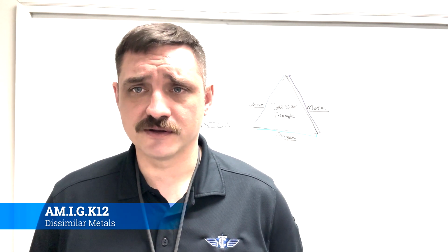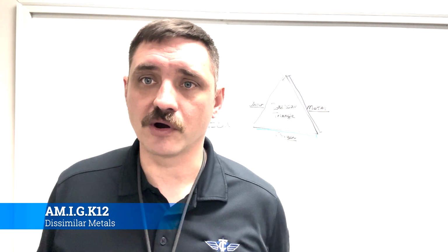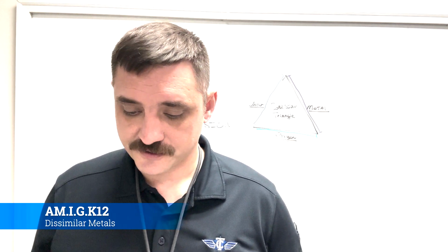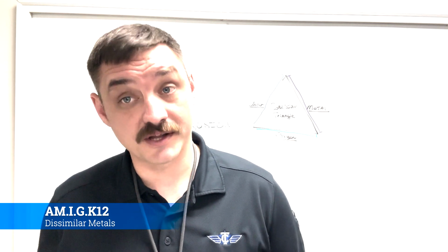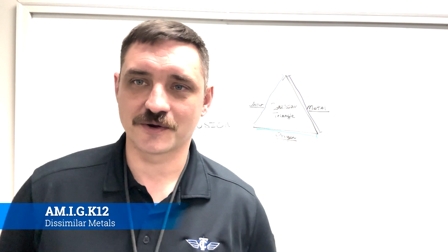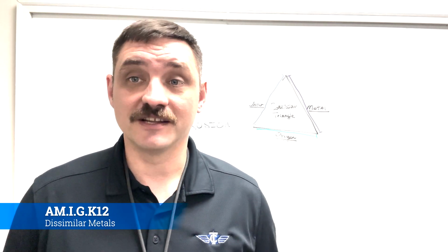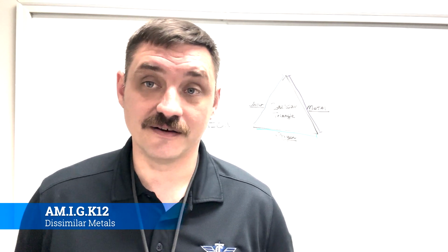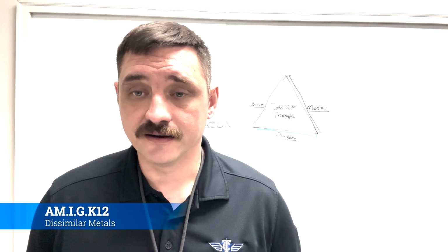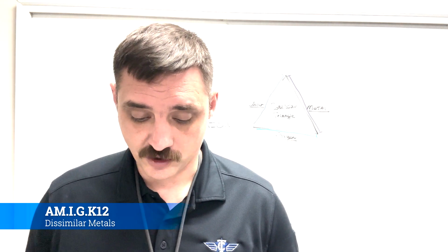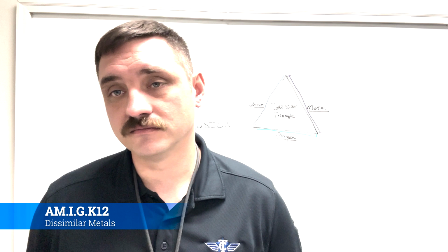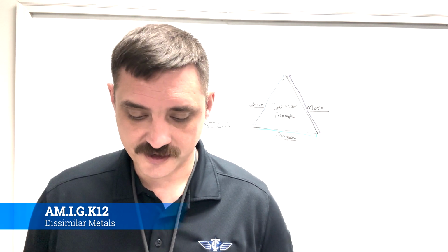Both metals don't react to the grease, and the grease can stand in the middle and keep those two metal pieces apart. That's an option. Sealant, you'll use a lot of sealant. We haven't got to the sealant part of our lives yet in this course, but you'll see a lot of sealant of different varieties all over the place. Black RTV, B1.5, those types of things.